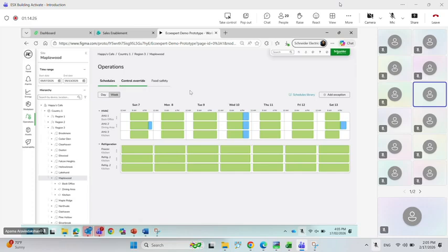I would monitor the power consumption against the temperature achieved in the freezer. And I'm giving an insight to the customer that there were these many instances in the last week where the power consumption remained high despite achieving the temperature, or the power consumption is consistently high, but the temperature is not achieved. So just pulling out data simply through power tags or meters and sensors, but the system is correlating this information.